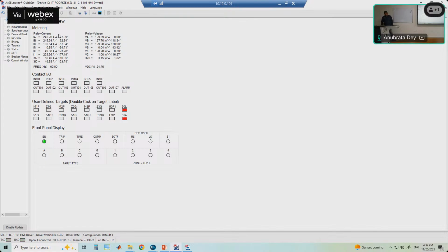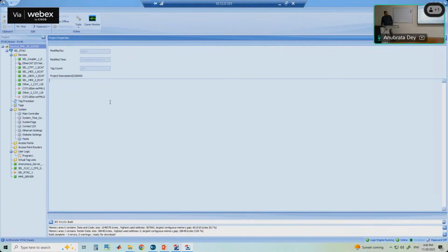If we want to give it back to the RTDS directly, we need to use that GTNET card. But now, to use the hardware device, we are sending the data of this device using GOOSE communication to one of our Axion devices, one of the PMUs. So we are sending it over here.